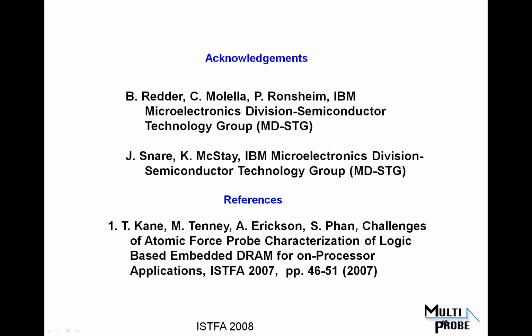Okay, so the NCVS on the test structure was a 2-probe measurement between the gate and the source drain region. That's all that was necessary, and it was on an SOI sample. Can you talk about the technology? So that's a 65 nanometer structure.